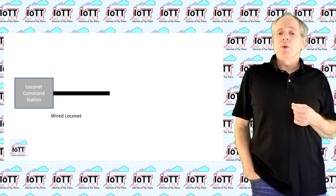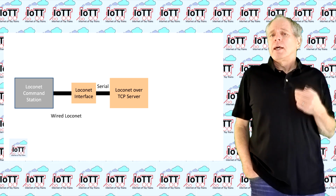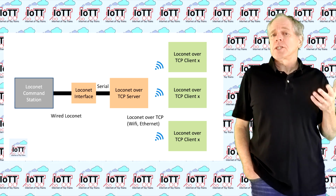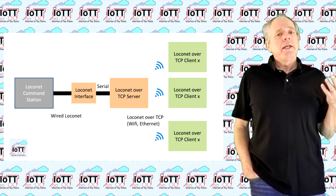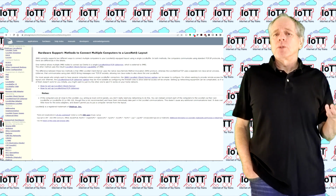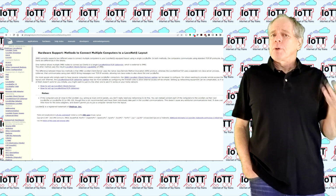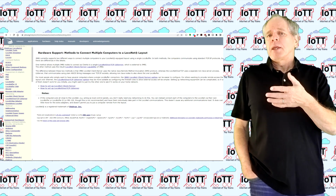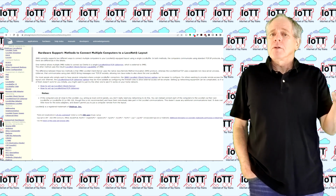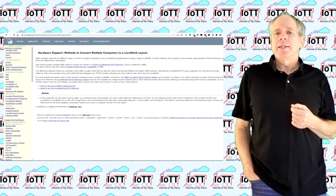Maintaining the tree structure of Loconet, the server connects to the Loconet that originates from the command station, and the clients then connect into the server. If a command station supports Loconet over TCP, it usually provides a server. Software like JMRI has typically both a server and a client, so it is possible to interface to the wired Loconet and provide a Loconet over TCP server, and on the other hand, JMRI can also connect to a Loconet over TCP server on a different machine using the built-in Loconet over TCP client.